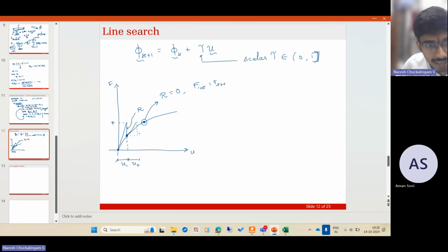But corresponding to the second iteration increment, you get a new residual. So going from here to here is the update, the stress update. Similarly, going from here to here is the update. Finding this is the invert. This part is inverting and finding the tangent. Sorry, increment. So you reach here. Then again draw a tangent, and we slowly converge to this point.